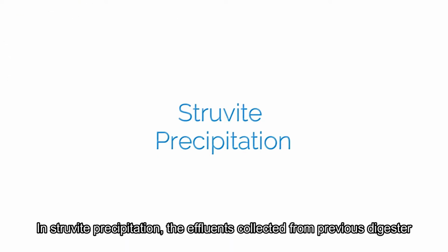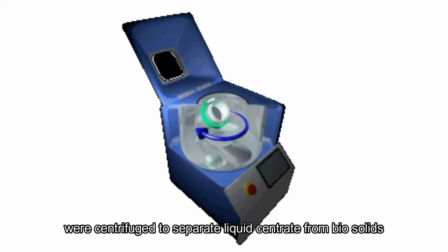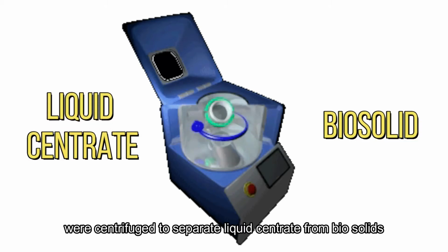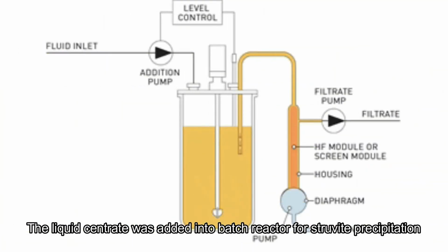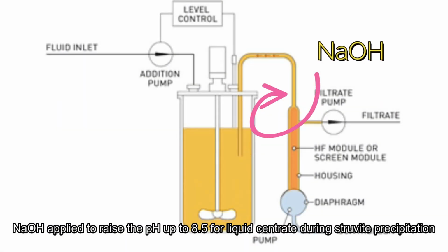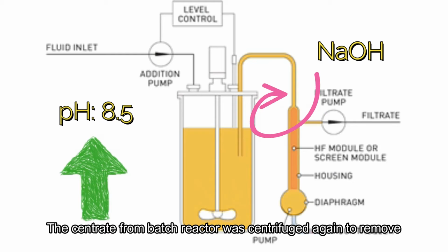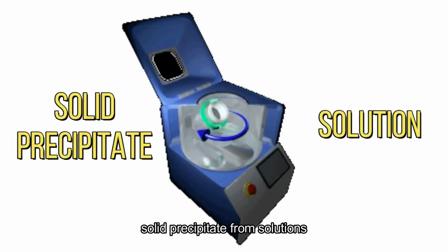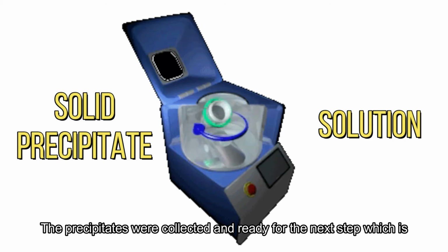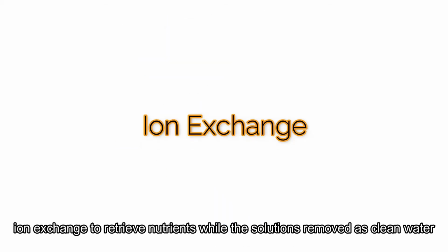In struvite precipitation, the effluent collected from the previous digester was centrifuged to separate liquid centrate from biosolids. The liquid centrate was added into a batch reactor for struvite precipitation. Sodium hydroxide was applied to raise the pH up to 8.5 for the liquid centrate during struvite precipitation. The centrate from the batch reactor was centrifuged again to remove solid precipitate from the solution. The precipitates were collected and ready for the next step, which is ion exchange to retrieve nutrients, while the solution is removed as clean water.